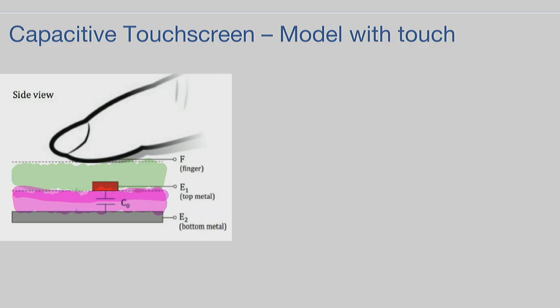Our finger is conductive. That's right. So essentially, when we touch this touch screen, we are, in practice, introducing a new conductor. The area that we touch with the finger represents another conductor. Now, if I have another conductor, my finger, touching a stack of electronic materials with dielectric and metal, then I introduce a new capacitance. And where is that capacitance represented?